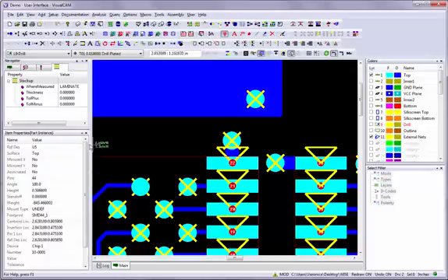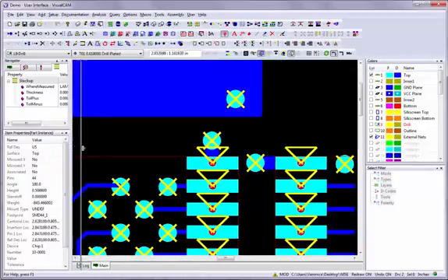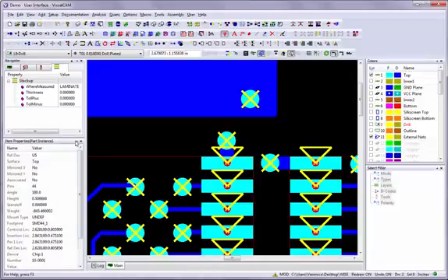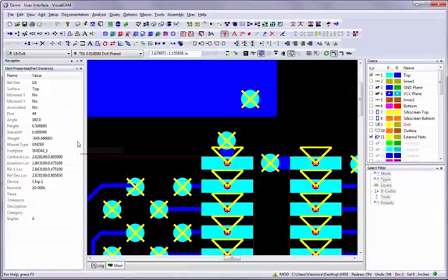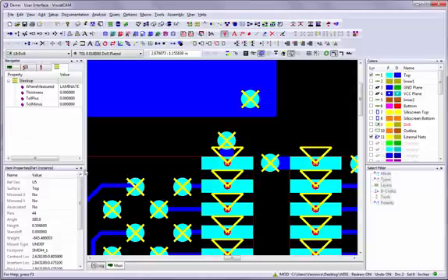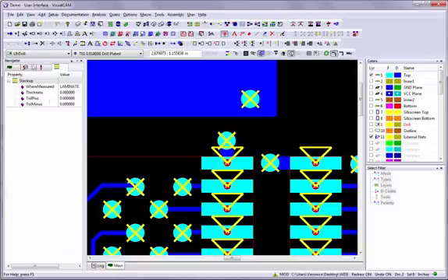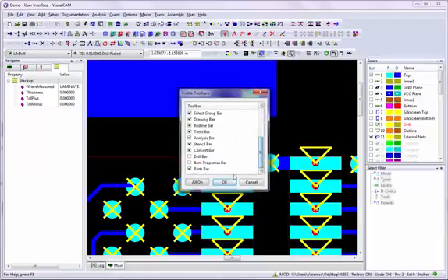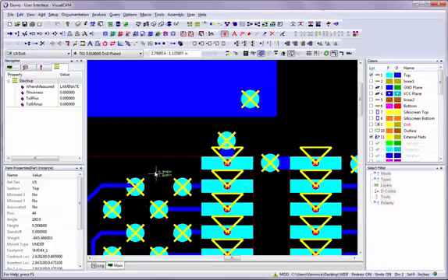Like the navigator, you can resize the height and width of the Item Properties window by left-clicking and dragging the edges until the desired size is reached. To expand it to fill the height of the main window, left-click on the up arrow, then reduce its size again by clicking the down arrow. To close the display, click on the X in the upper right corner. The window will automatically appear again when a function requires it, but if you want to unhide it before then, go to View Toolbars to make it visible again. Item properties can also be docked anywhere within or to the sides of the main window.